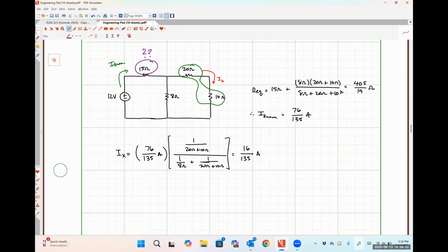Is it because the current's the same no matter if it goes through it or not? So I think you phrased that a little bit confusingly, but the gist of the answer is correct. So essentially, we know that all of our known current flows through that 15 ohm resistor, so it doesn't split when it sees that guy. So the current flowing in right there in green is this same current that's flowing out that then splits among those two paths. So if you just have the current flowing into a resistor that's connected in series, the current doesn't have an opportunity to divide, so it shouldn't show up in your current division relationship. Hopefully that makes sense.